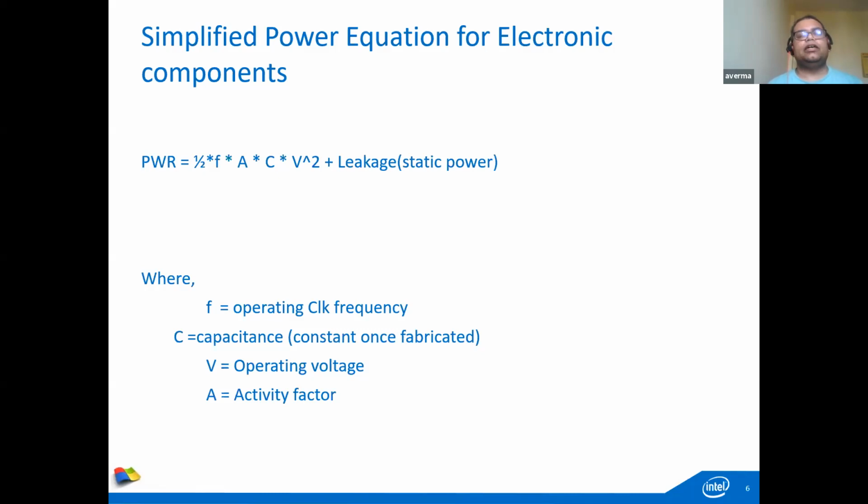For example, if some important message came on the WLAN, or something else is configured so that you press one button and it should come out of the sleep state, some wake circuit will remain on, and the rest will all get power gated, right? So in the sleep state, the contexts of these applications are saved on the DRAM, and the rest is all power gated.